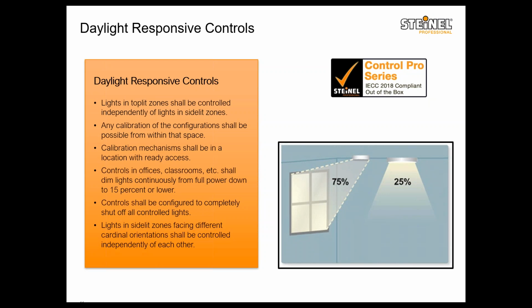So these daylight responsive controls haven't changed, but they have introduced a couple of new topics that are quite interesting. The first one is that lights in top lit zones shall be controlled independently of lights in side lit zones. I don't know about anyone on this call, but I haven't run into that many of such applications anyway. So I guess they were just trying to cover all the bases.